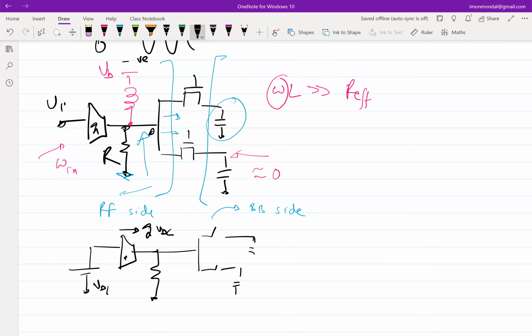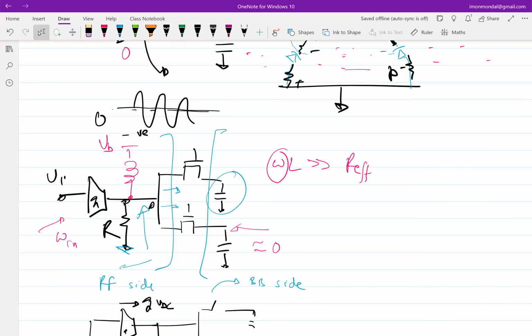right? If you are not taking care of, let's say the mixer in this example, what is the optimum operating point of the mixer? Let's say you do not have any other information. You want to ensure that the swing here is such that it doesn't clip on either side. So what should be approximately VDD by 2, right?